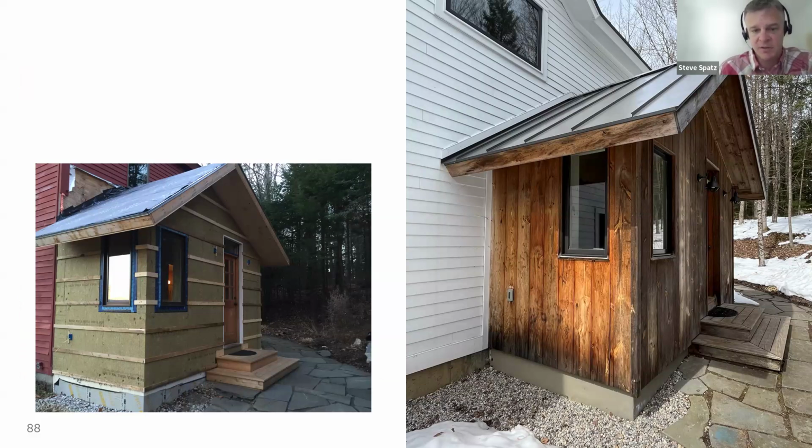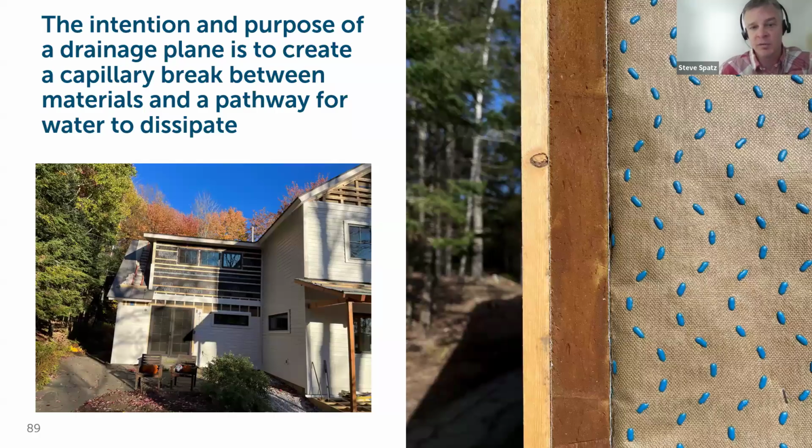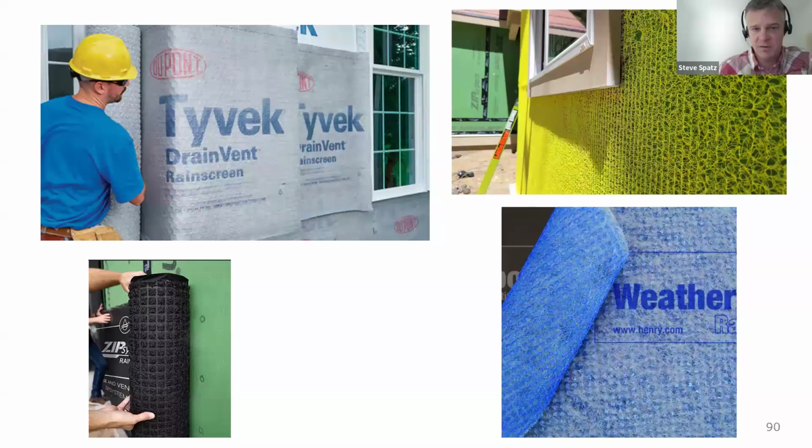So, as the question noted earlier from Keith, you just need separation from those exterior finishes to the materials behind it. So you don't need to worry about directing where water can move. Again, just that small capillary break of the material to the substrate is enough that any vapor drive occurring through that material just has some circulation and is not in direct contact with the material that could be damaged if it gets wet and stays wet over time.